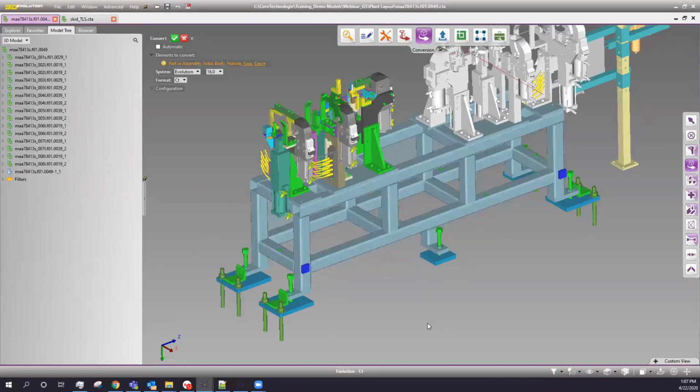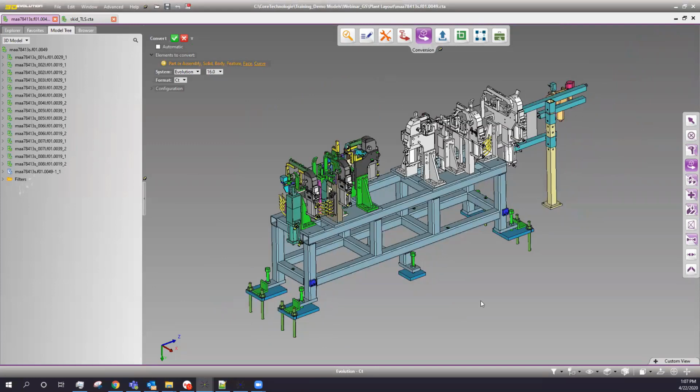So the end goal of this one, what we've done is we've optimized a process for JT files. And what we want to do is keep all the specific mounting points as BREP geometry, so you can have exact representations and exact measurements of where the details are and how it'll mount precisely. And then all the rest of the geometry is just used for spatial constraints and to hold a space in your assembly.